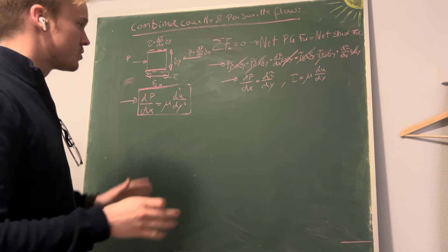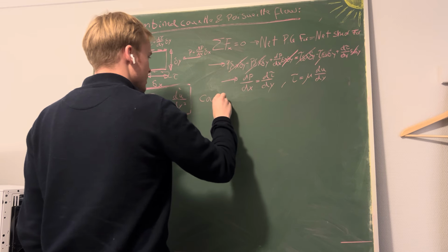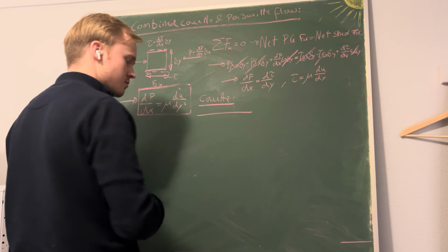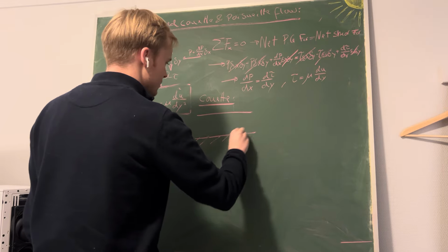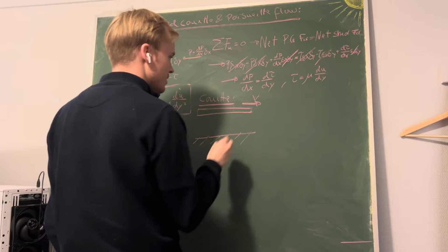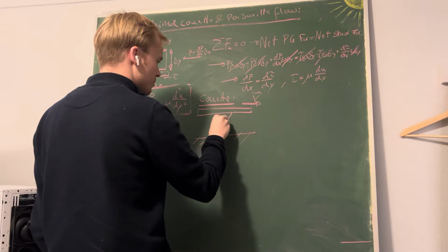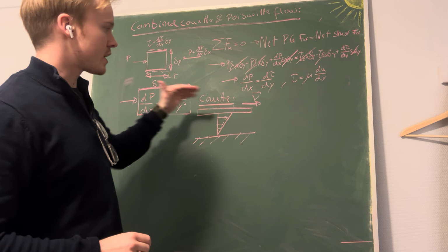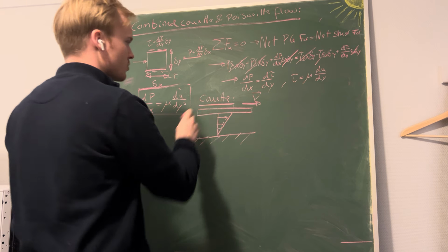But now I'm going to draw up the two cases. So now we have both. We have Couette, which we established in some videos before, where our top wall is moving with the velocity v. Then our velocity profile is a linear function, and this is without the pressure gradient. It's just the shear that is dragging the fluid elements along the top wall, making them move, right? So this was Couette flow.